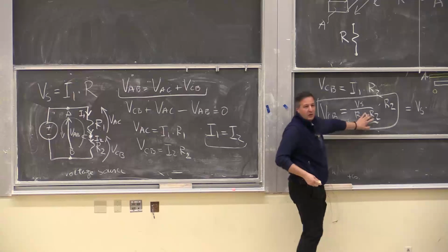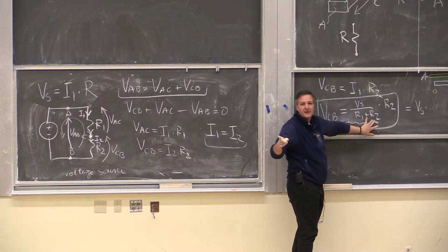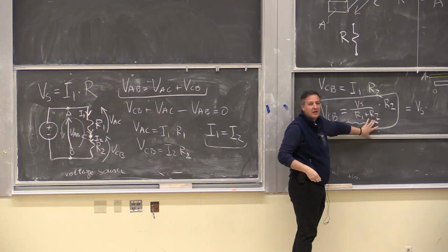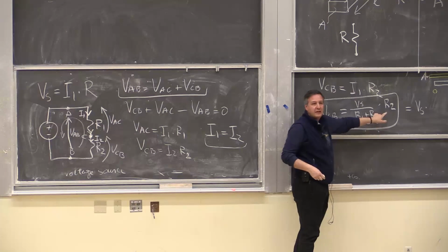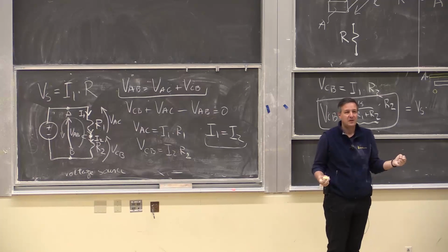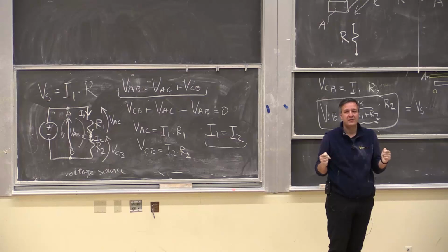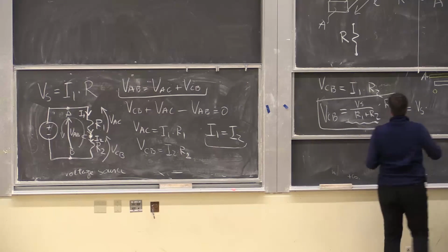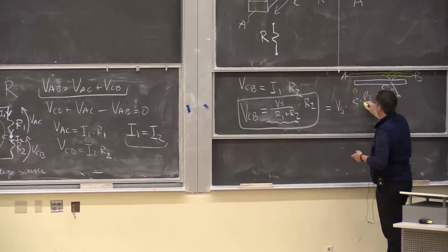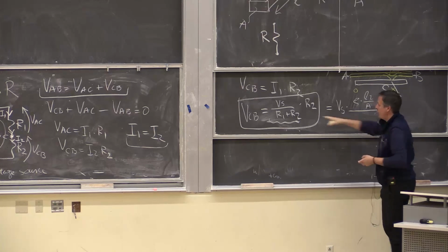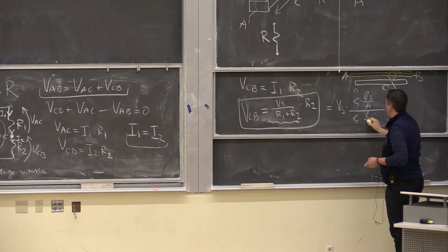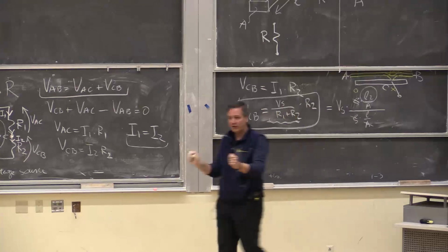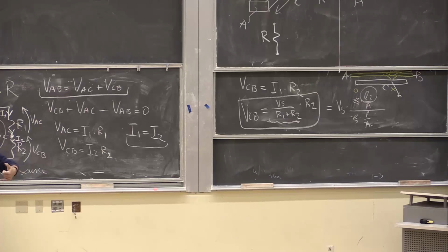Okay, going back to here. What did I do here? Any volunteers? That's right, but did I get some physical quantity that I wanted? I was looking for a coordinate. Did I get it? Yes? It is encoded in R2, right? Remember, R2 is rho L2 over A, over this R total, which is rho times L over A. So I'll cancel these, and I have my L2. Now I've encoded my position along the wire into the voltage that I'm reading out.